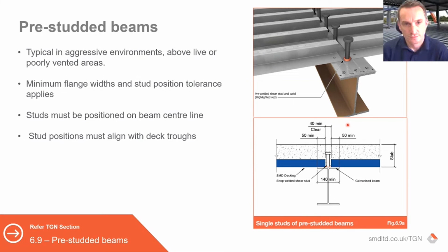So we've talked so far very much about studding on site. So what can we do? What can't we achieve? There are situations where the studs may be put on the beam prior to attending site. So they'll be put on in the fabrication shop, the steelwork contractor's factory, and they will be welded into position such that when the decking is supplied and the deck contractor comes along to fix, they're fixing around that. This is just a number of key things required in relation to that.